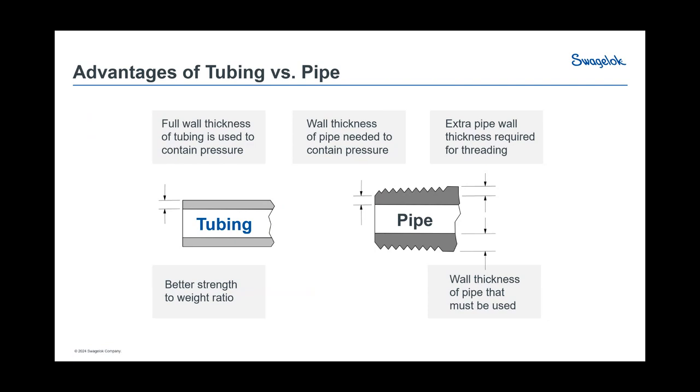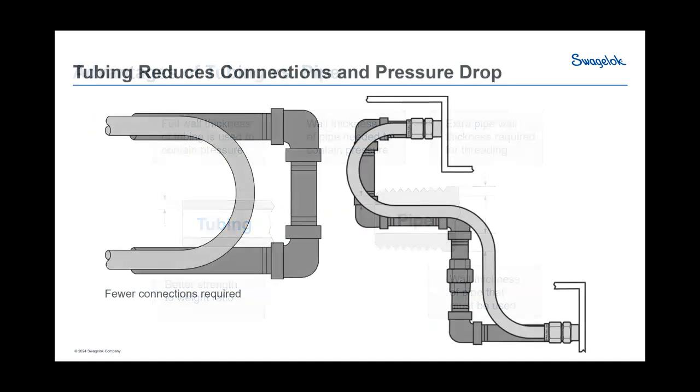And you can get pipe in stainless, and stainless is the preferred material over carbon steel. It does start getting much more expensive. You are paying for the steel that goes into tubing or piping. It's bought by the pound and sold by the foot when they draw it out. So it is much heavier, so it's much more expensive.